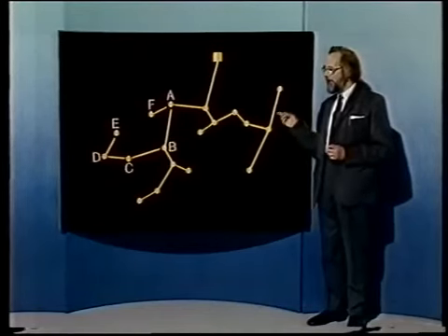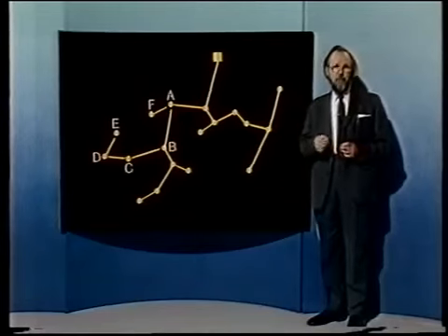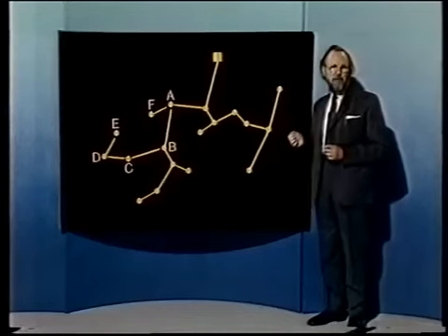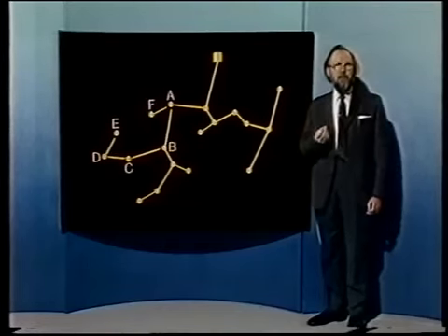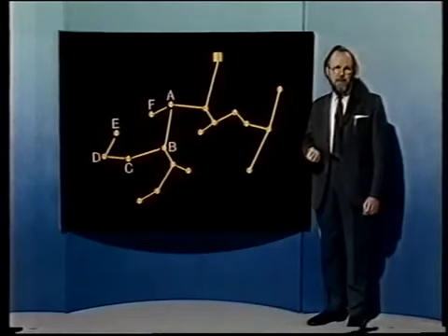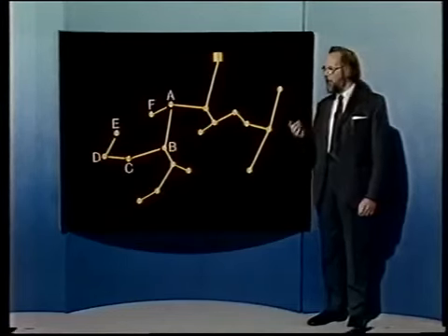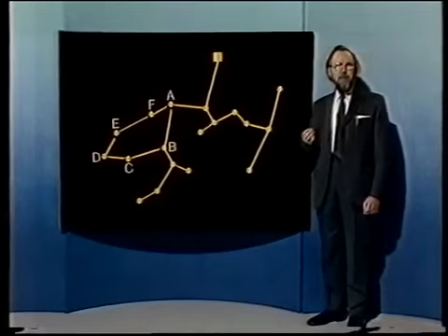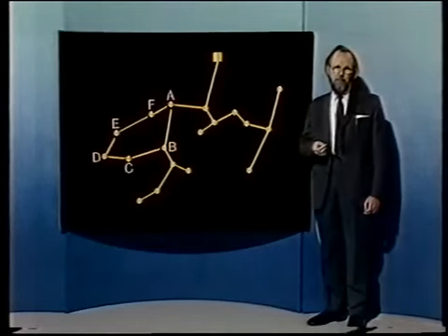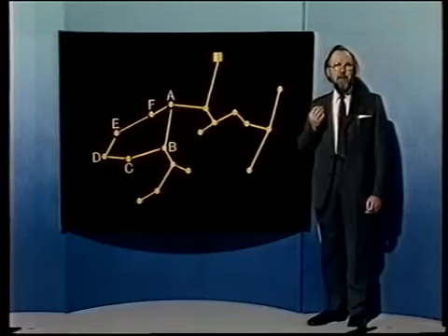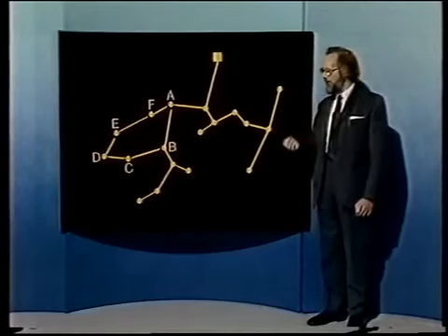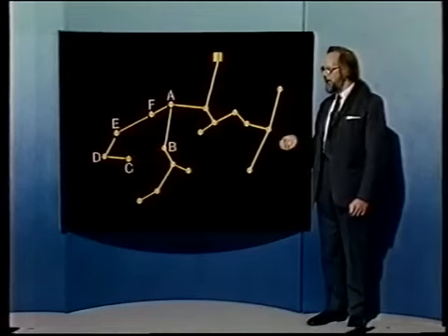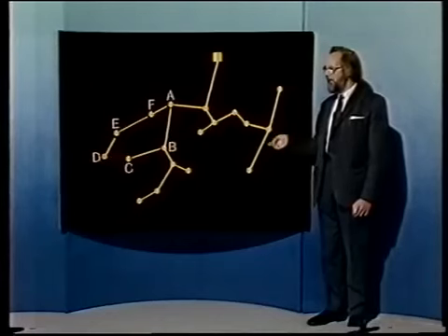Now we have the branch AB instead of FB. What we have to do is to look at each vertex in turn. So let's start by taking the vertex F. And we look for the nearest vertex which is not already adjacent to it. Let's suppose it's the vertex E. We then introduce a new branch, FE. And of course, this gives us a cycle. We've got A, B, C, D, E, F, and A again. And then we shall consider trees got by eliminating each branch of the cycle in turn. So we might eliminate AB and get this tree, or instead we could eliminate BC and get this tree, or eliminate CD and get this tree.